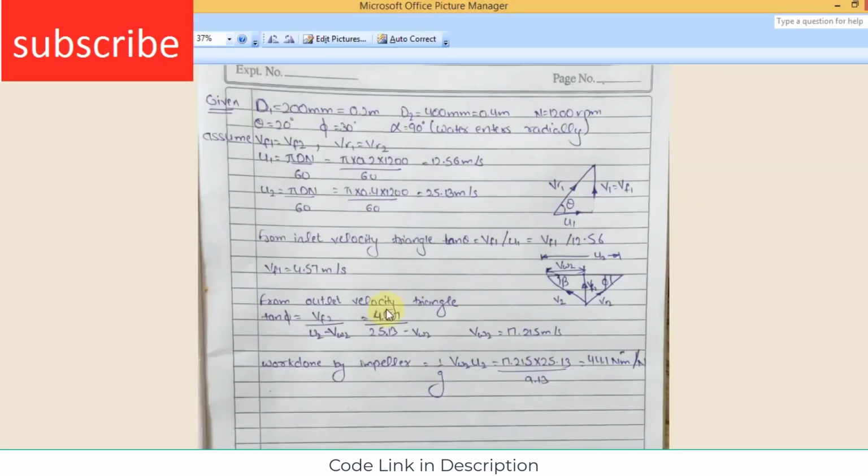So first of all, what I have done is that I solved this question. Here D1 is 200 mm, that is 0.2 meter, and D2 is 0.4 meter, and that is 1200 rpm. Remember, all these conditions are given. Now Vf1 equals Vf2 and Vr1 equals Vr2. I assume that. Now first of all, I calculate the velocity at the blade inlet, that's 12.56 meter per second, and velocity at the vane outlet, that is 25.13 meter per second.